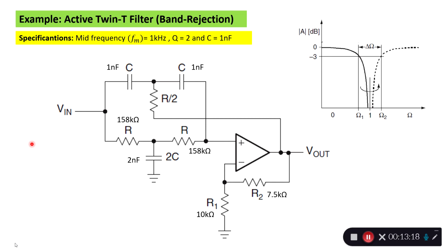The next step would be to simulate it, to see that we actually get the overall transfer function characteristic of it, and that it filters out the frequency here of 1 kilohertz sufficiently. Or do we need to do some tweaking of the filter or have a higher order?